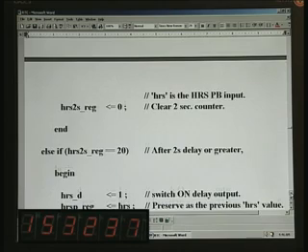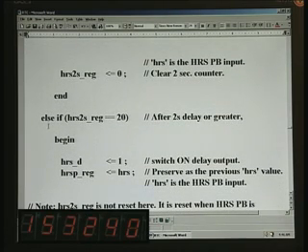for incrementing that display, right. And now next is if hours 2 second, suppose it starts running, we have not spoken of running yet. If it starts running and we look for the value 20, right, this will give exactly this time base, which is 0.1 second once again here, and after 2 seconds, 20 would mean 2 second delay or greater. This is how you reckon the actual delay. So this is the running counter for keeping track. So it will start from 0, 1, 2, 3, it will start advancing from 0, 1 and so on, only if you press for at least 2 seconds, only then this will come into play.